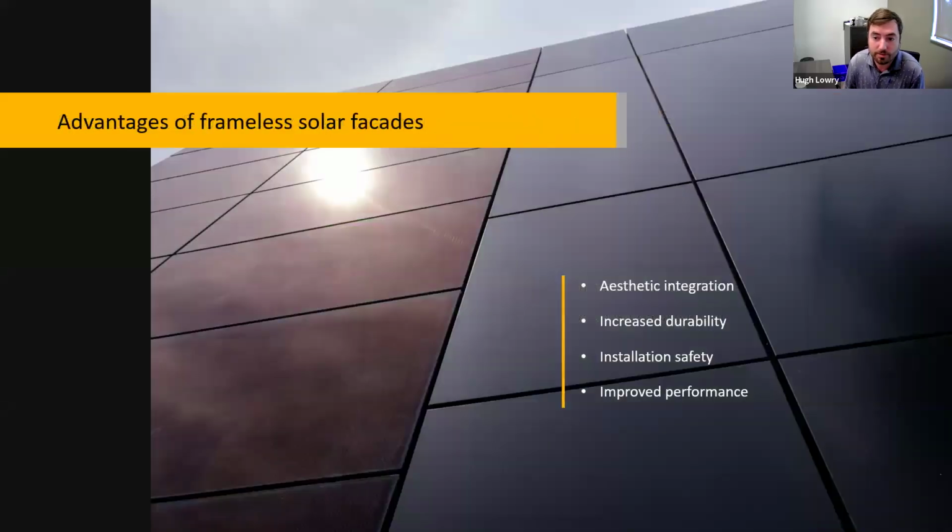So there's another technology that recently appeared on the market, and it's one that we feel helps improve both performance and the aesthetics of BIPV facades. Traditional solar panels have aluminum frames and brackets that don't always fit in with the design of the building. So frameless panels are now available. Frameless panels are composed of solar cells sandwiched between 2 sheets of glass without frames. They can be mounted mechanically using bolts through glass or clamps, or chemically using adhesives, a variety of mounting techniques.